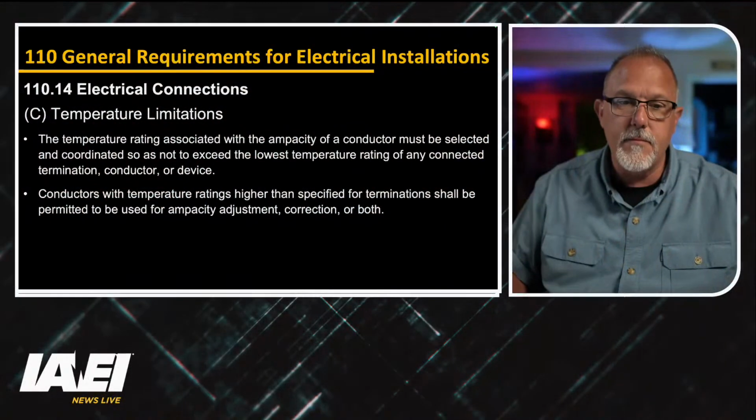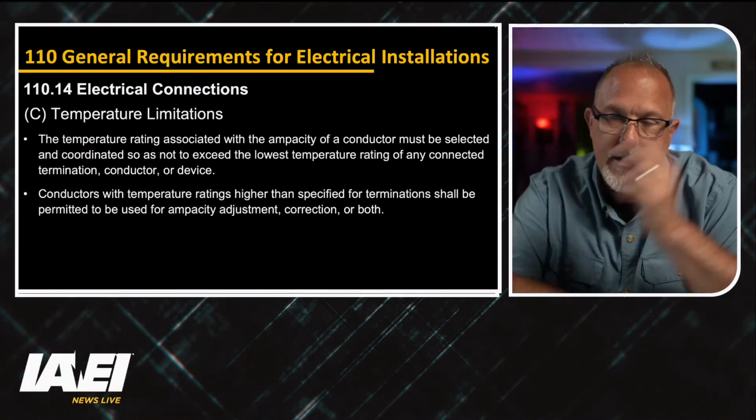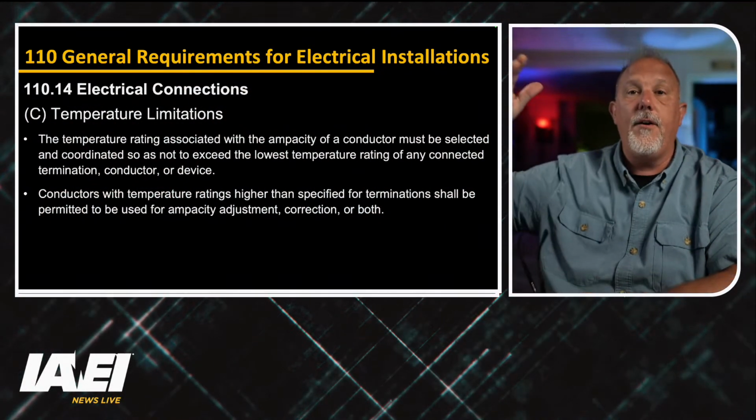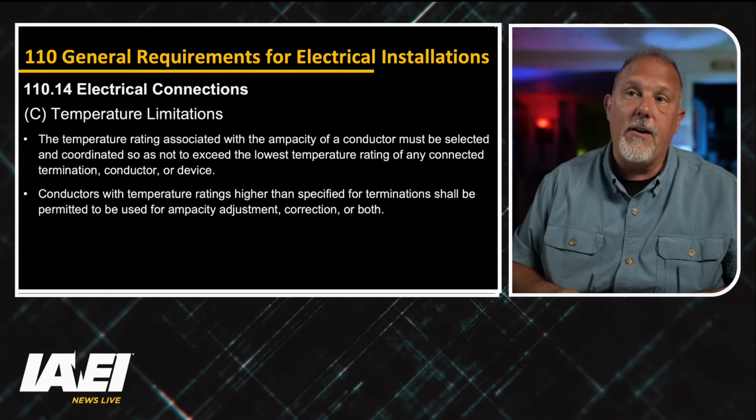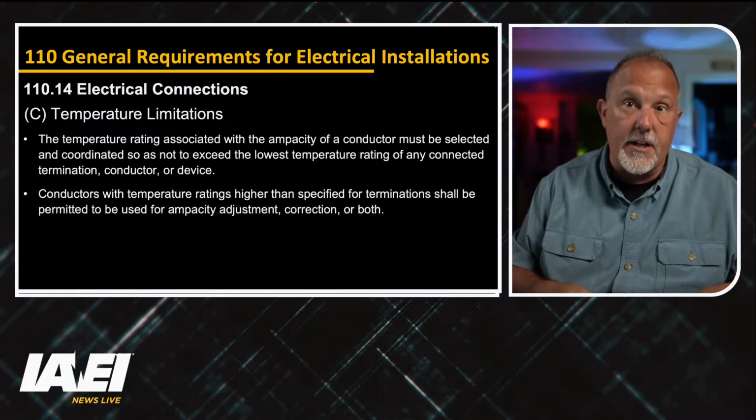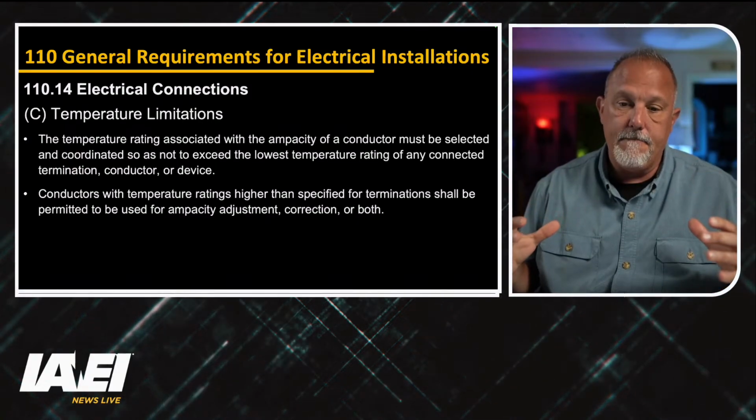All right, so we went through in 310.15 the adjustment factors. Just make sure I got all of them. 310.15. Then 310.16 is your table. Now, the other thing we must remember is that in 110.14, we already talked about a little bit, the equipment that I'm landing the conductor in, this is where I argue is the circuit ampacity.